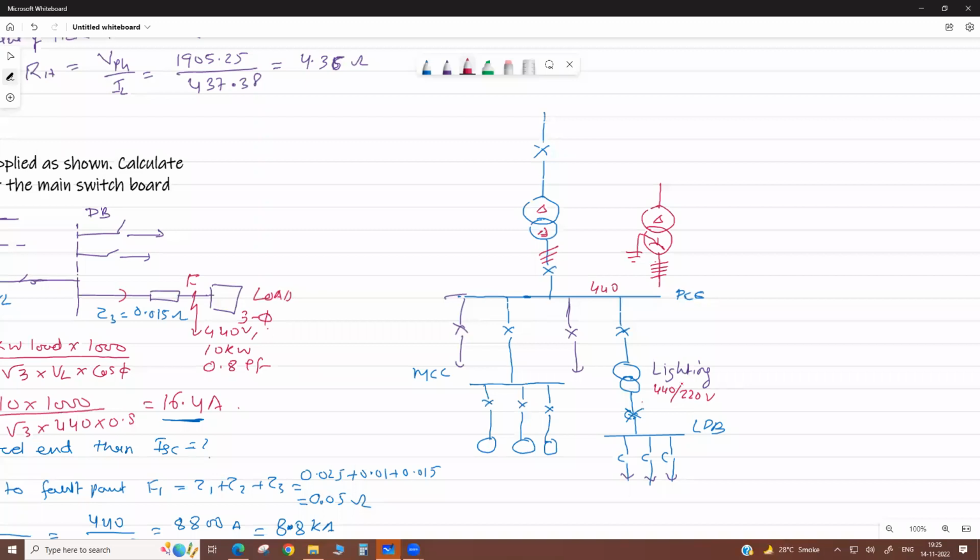We get a desired voltage. But I will explain for your knowledge. Now in commercial utilities also, like in malls and industries, it is a usual practice to use the lighting transformer, even though this is a 3-phase 4-wire system. There are two purposes. Generally here it is not 415 volt; it is 220 or 240 volt also.